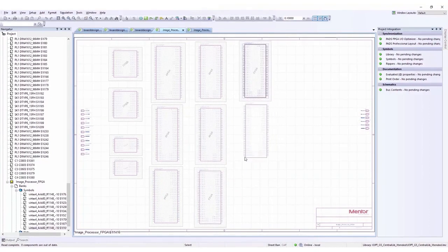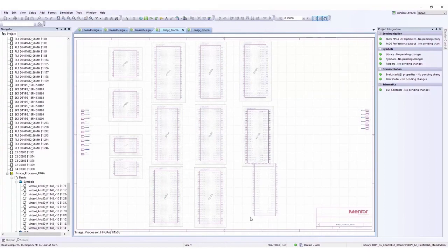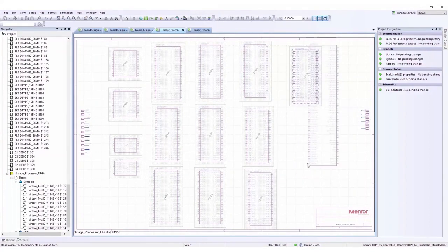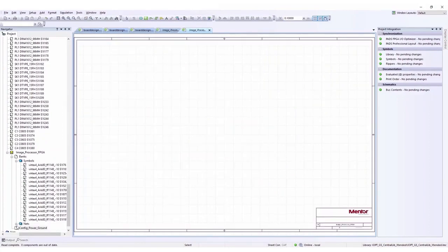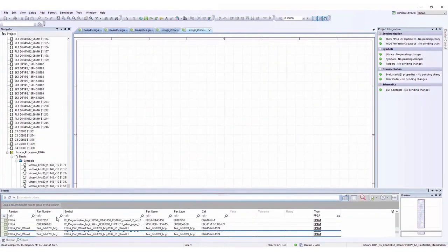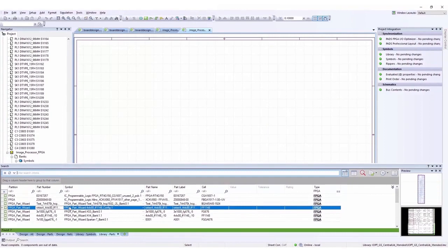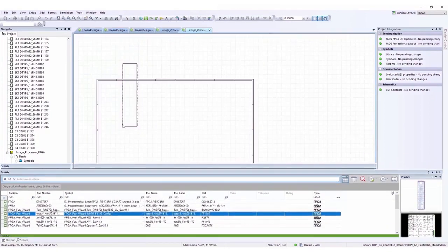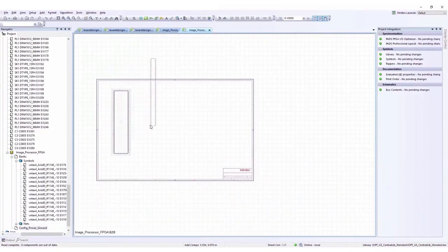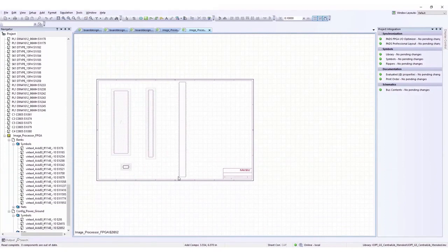The show alignment markers feature of the schematic editor happens to be pretty useful while placing FPGA symbols. The special field FPGA area, which allows easily identifying the FPGAs in the schematic, is a display option. It can be disabled if needed. You can abort the command and restart it. The next unplaced symbol will be available on your cursor.